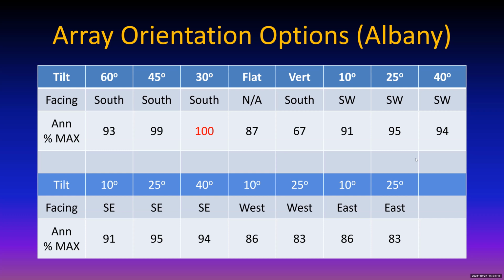So this just gives you a rough idea of what percentage you can get. If your module is tilted vertically in Alaska, you get a bigger percentage than you do if it's tilted vertically at the equator or in Florida. Florida vertical is just out of the question. You're down to about 53% or something. It's better to have it pointing north in Florida than be vertical. So, okay, let's see, got those, time to move on.